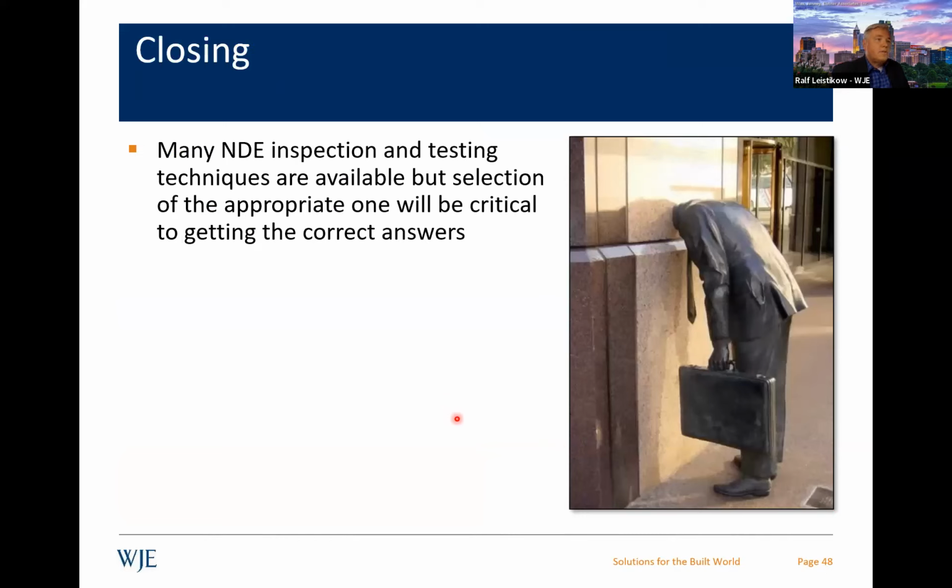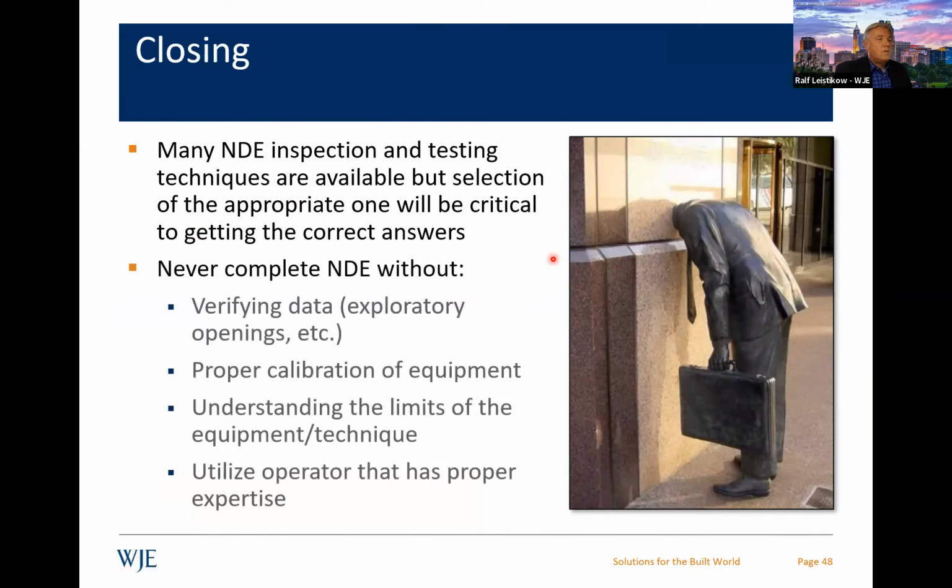So lastly, as Jason mentioned, many NDE inspections and testing techniques are available, but the selection of the appropriate one will be critical to get the correct answers that you're looking for. You definitely want to reach out to folks to get help determining what could be useful to you. And when completing NDE work, one of the things you have to look for is verification of the data. You can't use it like a black box. Doing exploratory openings is pretty important, knowing that you're doing the right thing as far as the equipment, as I mentioned before.